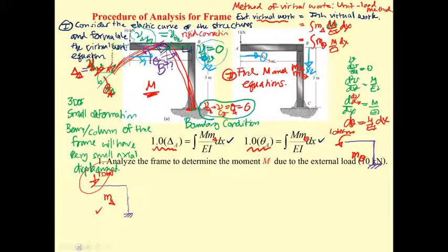Also, if you set the moment here, if you cut here and have the force here, you get this one for capital M1. And then you cut this one for the free body diagram of the 1 unit load. This is going to be m sub delta 1. The direction of the moment here and the direction of the moment here must be the same also. So every time you set up the coordinate, every time you set up the direction of the moment, just make them the same.